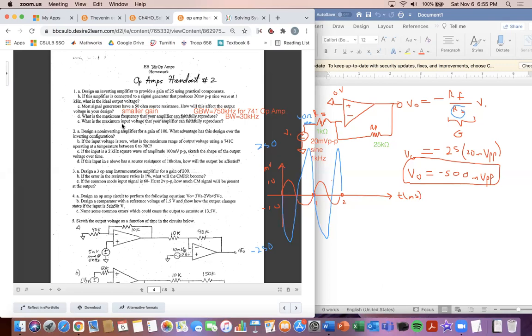is going to be, remember how amplifiers have a positive 15 and negative 15 normally as the supply voltages, so positive 15 and negative 15. When he said that, you recall that the output voltage can approach at most within 1 volt of those values. And so what we're going to have for output voltage, remember how we said it's equal to negative RF over RS times Vin.